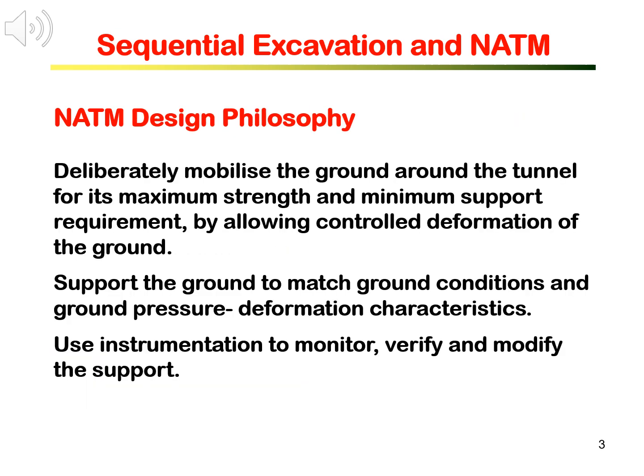As pointed out by Professor E.T. Brown, NATM can refer to both a design philosophy and an excavation method. NATM's approach is to deliberately mobilize the strength of the ground around the tunnel to the maximum extent possible. Mobilization of ground strength is achieved by allowing controlled deformation of the ground. Therefore, the ground will need minimum support requirement.